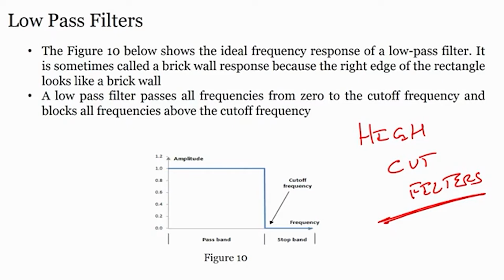The reason is not that they do not know how to draw the circuit. They know everything, they know high pass filter, band pass filter, they can draw in 2 minutes. It is not about testing their technical knowledge, it is about testing their focus, right. Whether you are reading the question, or you are assuming that you know everything and let us write immediately, right. So make sure that when you are asked a question in an interview to draw a high cut filter, do not start drawing a high pass filter. Understand, listen, process it and then draw. High cut filter is low pass, right, low cut filter is high pass. So do not get confused, alright.